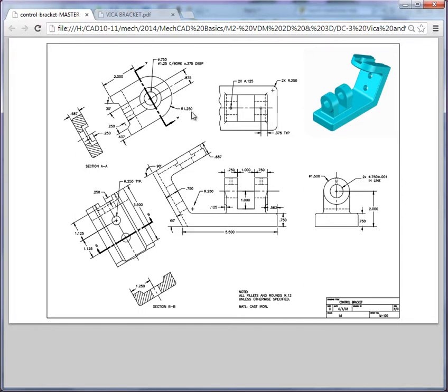We can use the fillets. We can also use, for this counterbore, the hole wizard. You have all the information that you need right here. Then you can see that we can simply create a profile to cut extrude into the auxiliary B face, as well as utilize the auxiliary B face to create a profile that will then be cut into the auxiliary A face. So let's take a look at how we'll proceed.